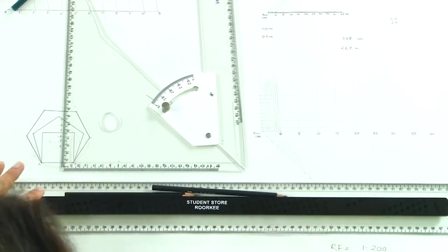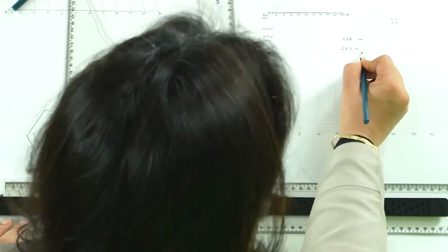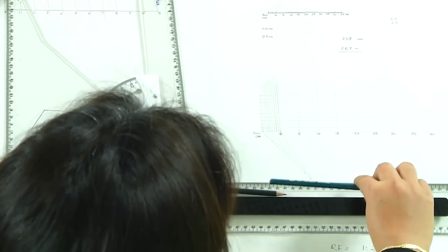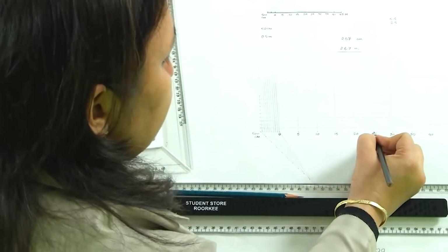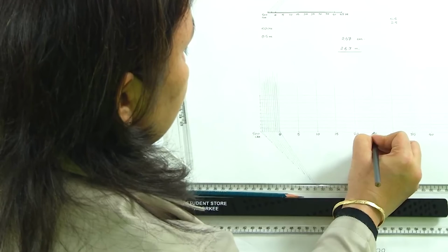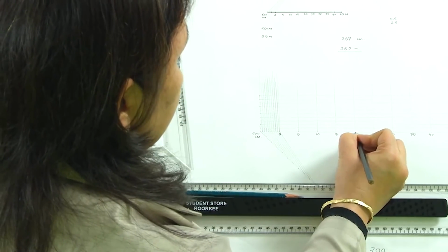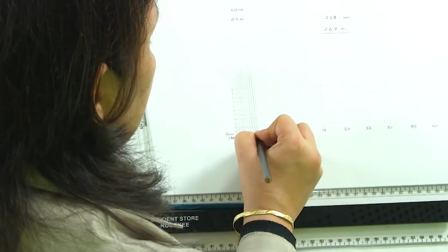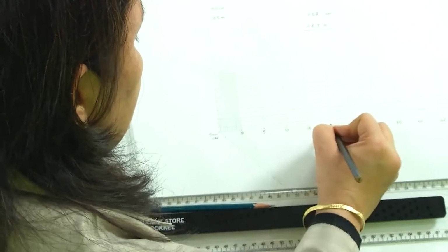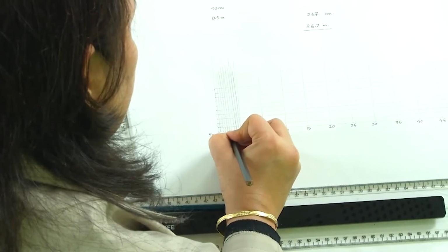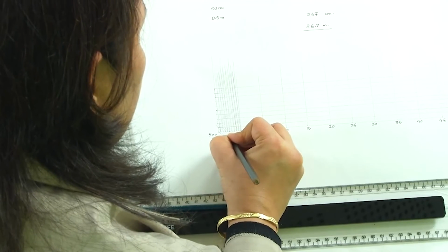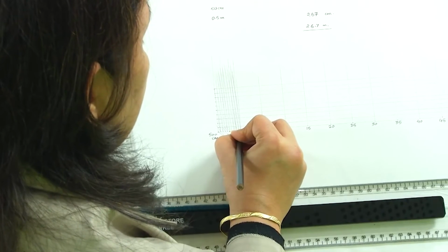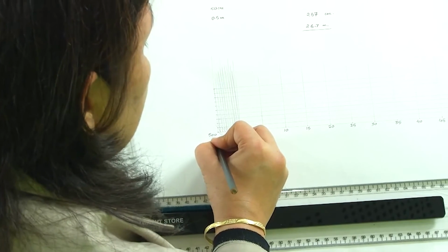So, what we now have to measure is, say, 26.7 meters. So, we have 25 meters here. Just look at it carefully. 25 meters here. Now, we could take 20. This is 500 centimeters. Each division, there are 10 divisions here, this is 50. If I take this, it is 50 centimeters, so it is 0.5 meters.